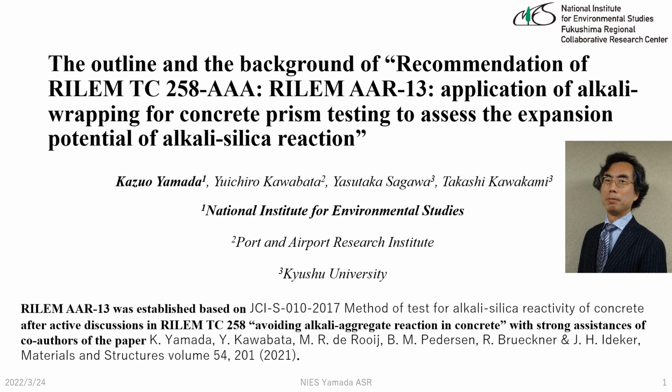My name is Kazuo Yamada from National Institute for Environmental Studies, Japan. I am now in charge of waste management after the Fukushima Daiichi nuclear power plant accident. For the final disposal, we need to prepare a concrete disposal facility. So we have to think about the durability regarding alkali aggregate reaction damage. So we need to develop a reliable testing method to assess the expansion potential of alkali-silica reaction.